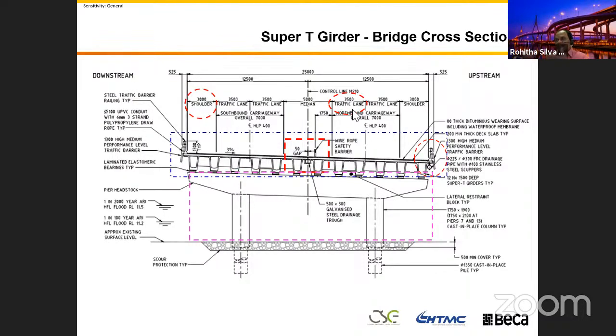The purpose of bridge designing is for traffic. When we are driving on a bridge, we divide the lane so that people will drive within that specified area, not right in the middle of the lane. So we have a lane width. On the edge, you can see a small element sticking out from the deck. That is the barrier. And next to the barrier, you can see another mark. That's the shoulder width. You will learn this later. The shoulder is 3 meters.